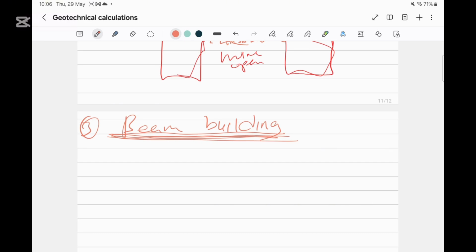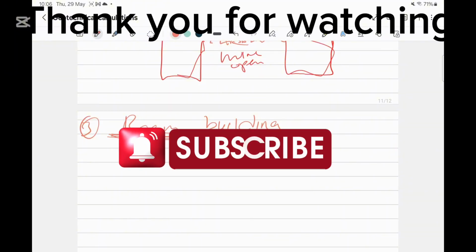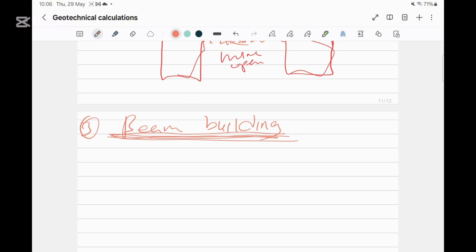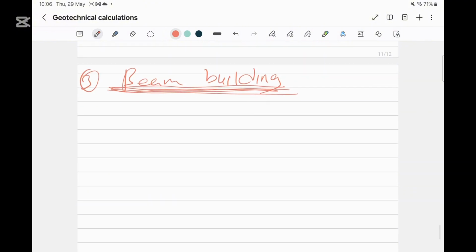You still use your roof bolts, but now they are just trying to maintain friction on the bearing planes, because that rock will have bearing planes but is not self-supporting. There's no self-supporting beam. Just go and look at the details of this one.